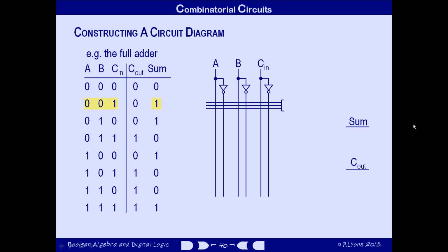So we add an AND gate to the circuit that detects when A is false. An AND gate produces a true output when its input voltages are all high. So we draw in a blob of solder that connects one of its inputs to a wire that has a high voltage on it when A is 0. Similarly, its second input is connected to the not B signal, which has a high voltage on it when B is 0.